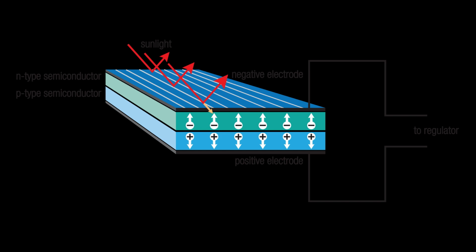As light enters, there are holes in the center where an excess positive will move downward into the p-type, and the electron will go up into the n-type. By this logic, it will allow electrons to flow. This is how current is generated by the solar cell.